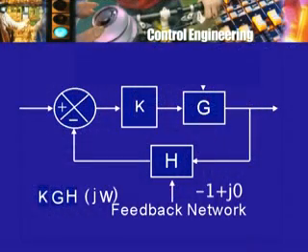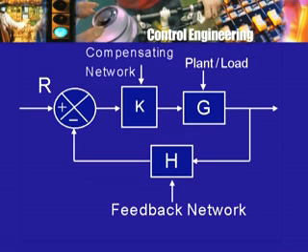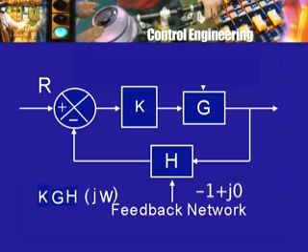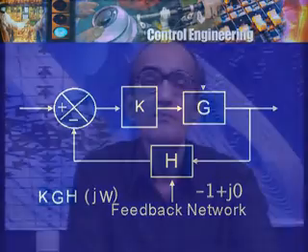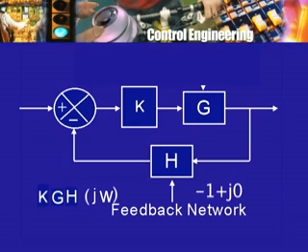Alright. So, now going back to our original problem, you have a closed loop control system where, going back to the old diagram, here is G, here is the feedback transfer function H, the difference device, the reference input R, and there is this gain K that corresponds to an amplifier of some sort and a converter of energy from one form to another, or changing a small voltage at a low power such as the reference voltage into a large voltage at a large power such as the DC generator that drives the motor. That is represented by K, and here we have G and H.